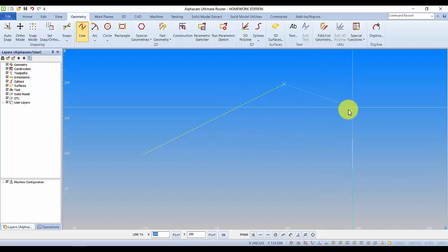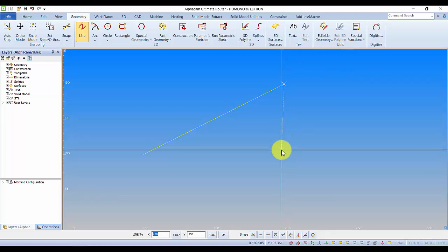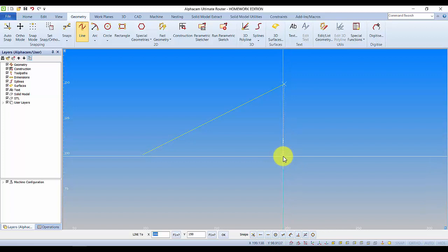You should spend a little bit of time familiarizing yourself with the coordinate system. The first value you put in, for instance in this case I'm going to put in a point 200, 100. 200, tab. That 200 is a value of 200 along the x-axis from left to right. And the value of 100, enter, is a value of 100 vertically upwards.